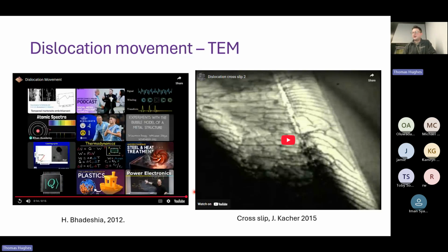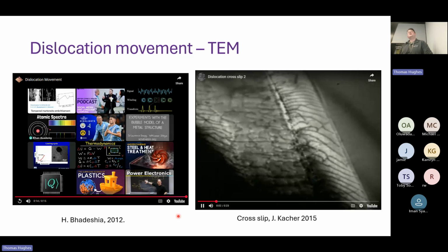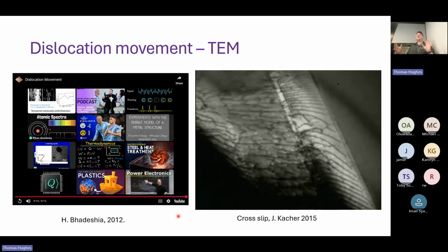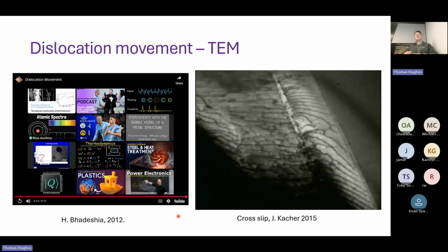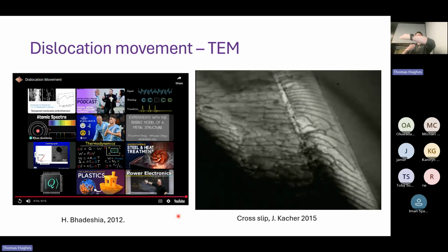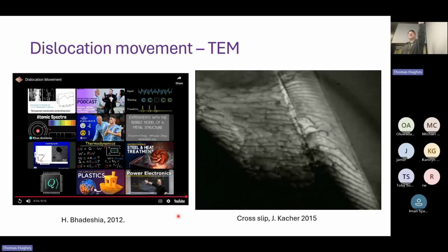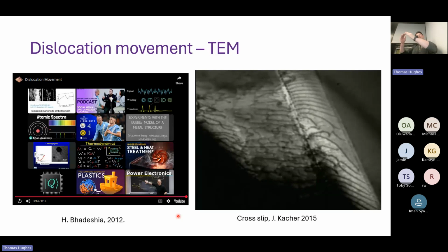So have a look at this one. This actually shows cross slip. You can see all your dislocations are doing something called pile up. In this case, you can almost think of them as having a charge. Essentially, they don't have one, but they essentially do in terms of the lattice tension and compression. You can see them all piling up like a big traffic jam up there. But this is how material is generally deforming. These are moving, and your material is deforming with them.